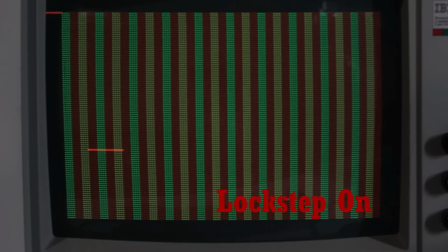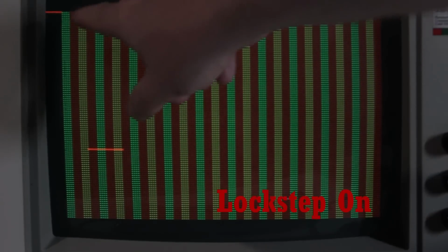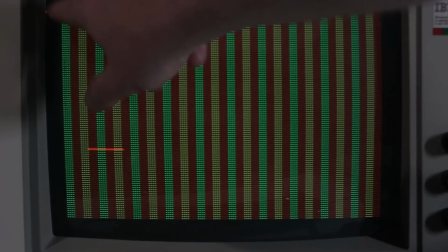And now I've got my code running with Lockstep, and as you can see, it's actually doing this register write to change from red back to black again at exactly the first pixel in the active region, down to the H dot. And if I rerun this code, just press a key to make that happen, you can see it's exactly the same place every time, totally reproducible, even if I restart the machine. Not only that, I've set it up so that if I press a different key here, it'll actually step forward by 1 H dot at a time. So in other words, half a pixel at a time, which is pretty impressive. You can see that happening now.